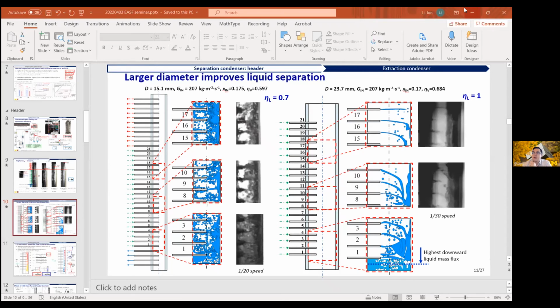Frost is much worse than ice if we differentiate them. Frost is so porous that it blocks a lot of the airflow. It also increases the pumping power for the air. But just from the heat transfer point of view, ice basically works as a thermal insulation.